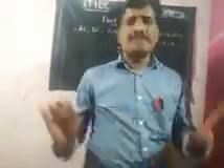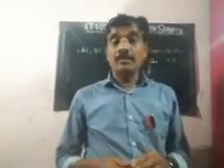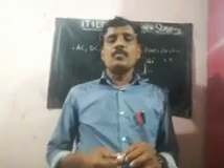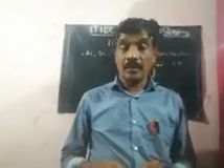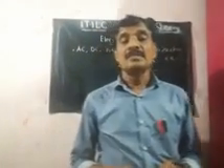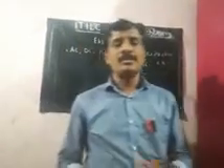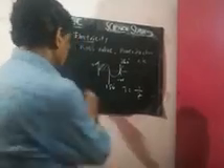By equation, the RMS value is the maximum value of the alternating current times 1 by root 2, or the maximum value of alternating current times 0.707. That's all. Using instantaneous values, we can also calculate the RMS value.